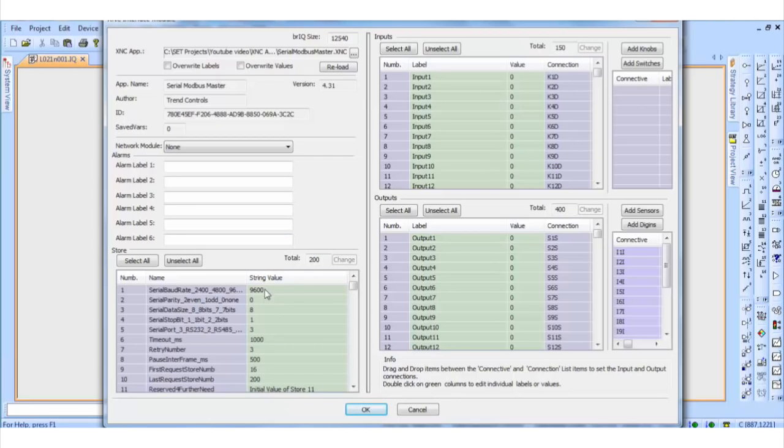The tricky bit is setting up the comms, which is these fields here, and then also to configure a string. Now in order to do both of those things, unfortunately we need to read a datasheet, but I can get a datasheet up and I can show you where to look. So the things that we're looking for are the serial baud rate, the parity, the data size, and the serial stop bits, and also the serial port, which I'll explain in a minute.